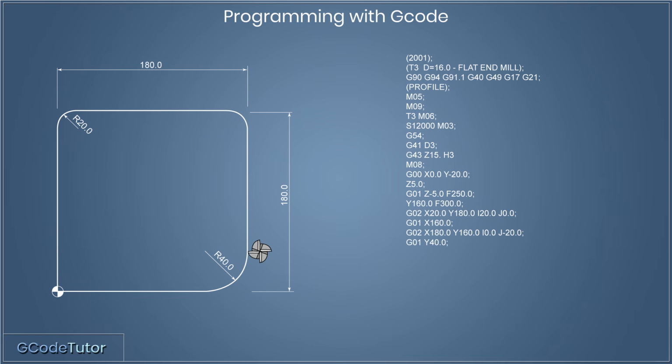Following that is another straight line move, so for that we switch over to G01 again. Now as we're switching between G01 and G02, we don't need to issue a new feed rate all the time. The original feed rate of 300 millimeters will stay active until we issue a new feed rate. Now sometimes we might want to slow the cutter down when machining radiuses. It totally depends on the way the machine handles the cut. So you might find it's cutting a little bit too fast on a radius and we can give it a slower feed rate as it approaches the G02 line.